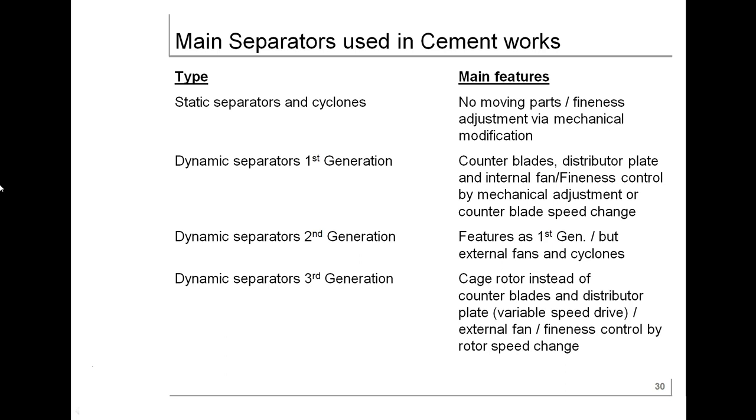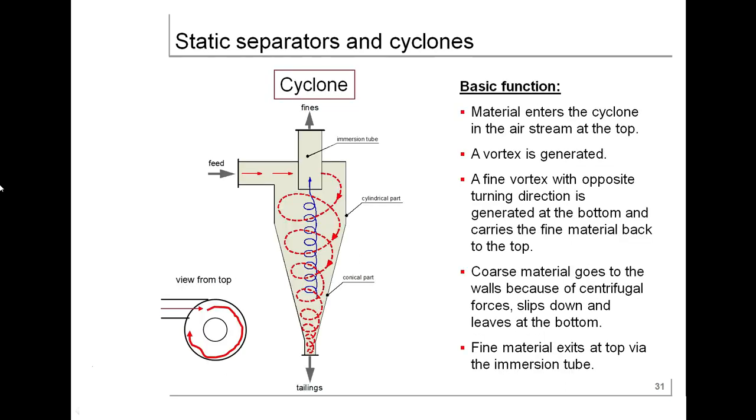Dynamic separators, third generation: cage rotor instead of counter blades and distributor plate. External fan; fineness controlled by rotor speed cage. Static separators and cyclones. Basic function.